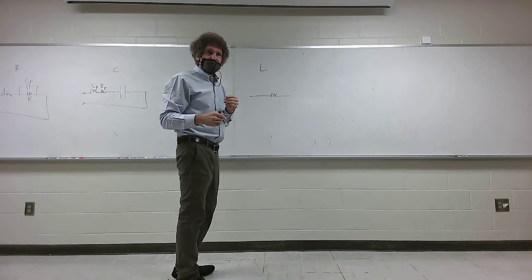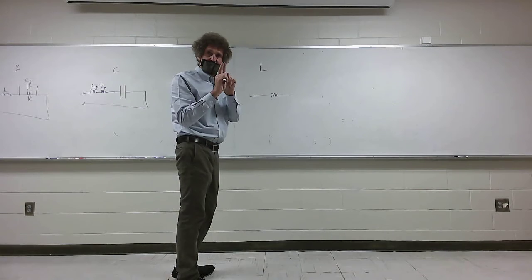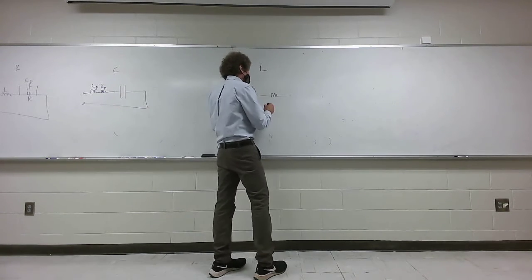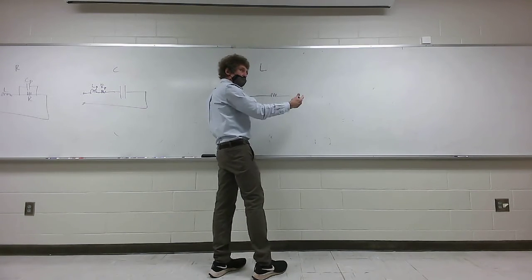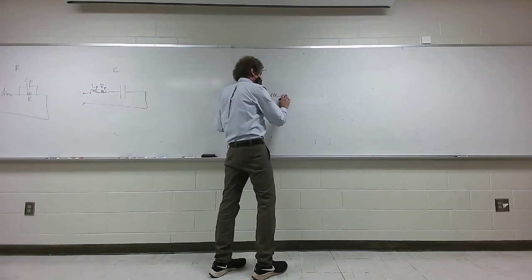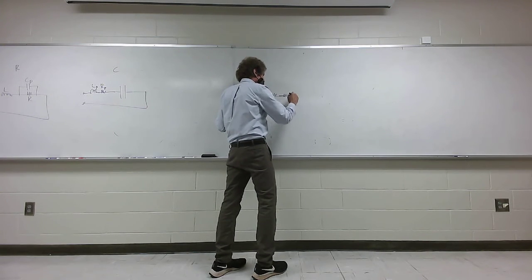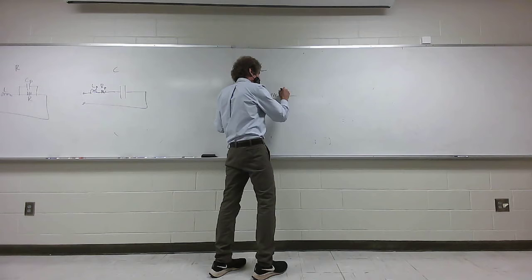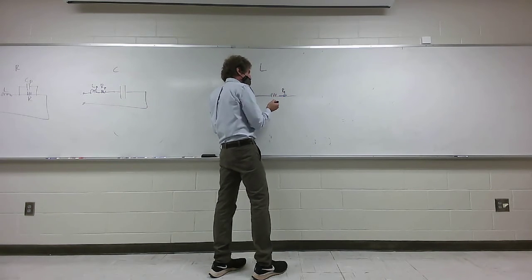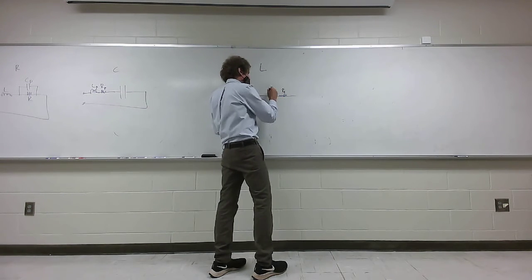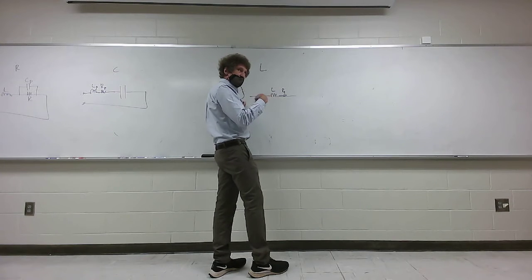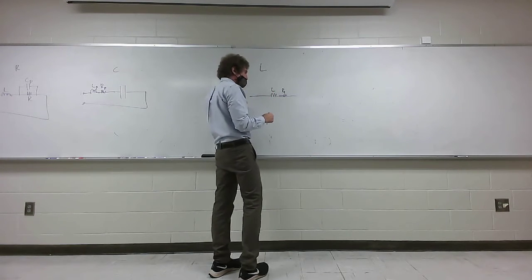Coils are used, just think of transformers when you think of inductors. When you have an inductor, because of the amount of wire, you're always going to have a resistance internal to the wire. It's a parasitic resistance you can't get rid of. It's associated with the gauge of the wire. The inductance has to do with the number of turns and radius of each turn.